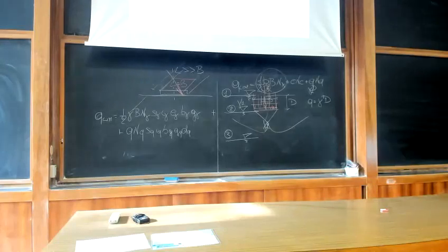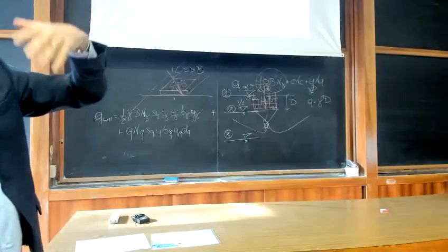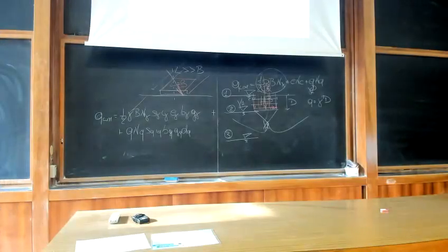You might find other authors providing you shape factors which are less than 1. So you have one author, Meyerhof, for example, which is quite famous, even if not recent, suggesting an expression of shape factor greater than 1, and other authors suggesting a factor less than 1.